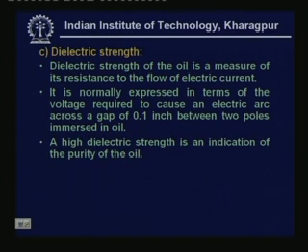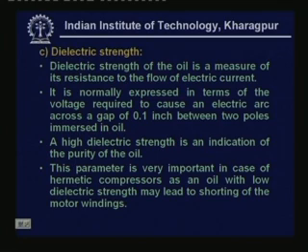A high dielectric strength is an indication of the purity of the oil, and this parameter is very important in case of hermetic compressors, as an oil with low dielectric strength may lead to shorting of the motor winding. So we have to have refrigerant lubricating oils having high dielectric strength, so that the shorting of the winding does not take place.